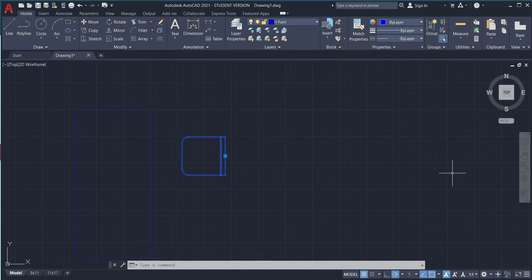Let's place it at the table. Now, you're going to find that interior designers like to be perfect in everything that they do. So I want to place this chair centered to the top half of the table. So I might have to draw a couple lines first to help me establish where the center is on this particular table. So I'm going to show you my method. You might have a different method that works for you. There's no right way or wrong way to do this, but this is just how I go about finding centers of things. So first I'm going to divide the table in half. So I'm drawing a temporary line right down the middle.